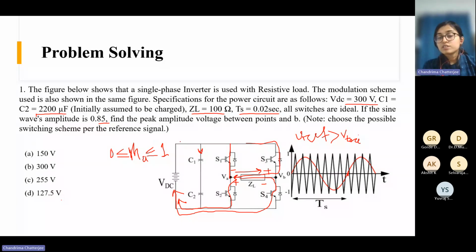Here you will get a proper, ideal DC, and the high frequency components, because you can understand this is a switched circuit. That's why there will obviously be high frequency components. Those high frequency components will pass through the capacitors, and will not get drawn from the battery, because then your battery will degrade. So from the battery you will draw only DC, maybe with slight ripple, and the high frequency components will be provided by the capacitors. Okay.